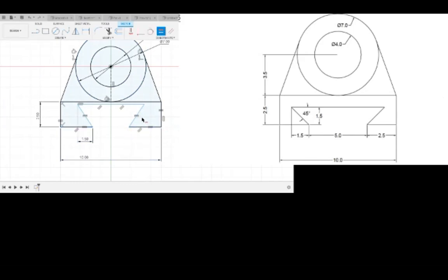They can't move. So the last thing you need to do is finish defining the dovetail itself, which will be easily constrained by just the last dimension here, which is the 1.5 that defines its height relative to the floor. Or not the floor, but rather this, whatever you want to call this line down here, the lowest line. We'll just go with that. So we set that to be 1.5, and there we go. Now we have our little sketch.